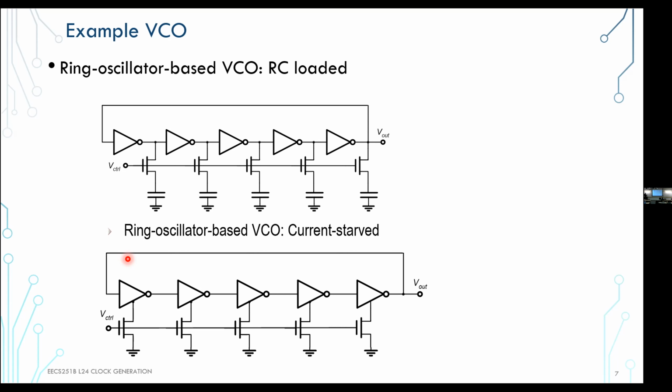Or I can do a little step response and then figure out the impulse from that. I can do a little step on the supply or on the control or on the current of the inverter stage as well, and sweep that across the timing edge.